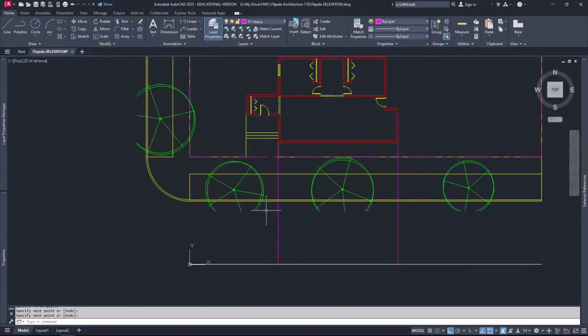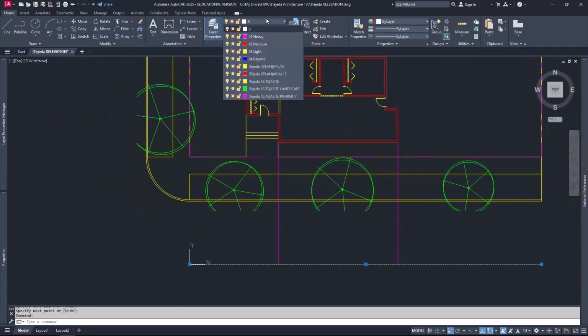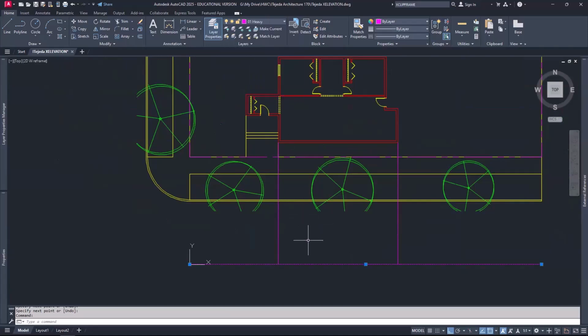Now, my building is 1 foot 6 inches above ground. I can take this line, and by the way, because this line also is in the foreground, I want this one to be heavy. Here's what I can do. Select it, put it on that layer. But if I really, really want it to be heavy, combining what we discussed in the last class about polylines and giving them a global thickness, I'm going to do that right now to this one. So I'm going to type PE, enter. Going to select the line, enter.